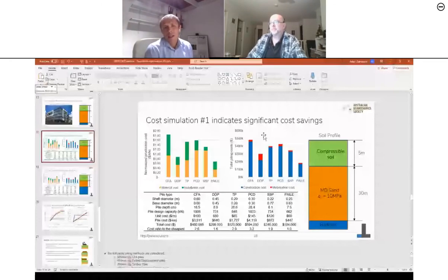may not necessarily be completely damaging the performance, because it relies on the bottom really. And the bottom hasn't been destroyed during that process, but there would be no verification of that capacity during the process of expanding the helices. So it can still be formed, but there would be less data from monitoring of the rig to confirm that the capacity has been achieved.